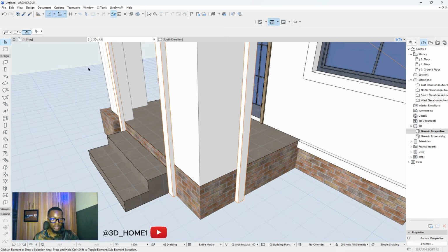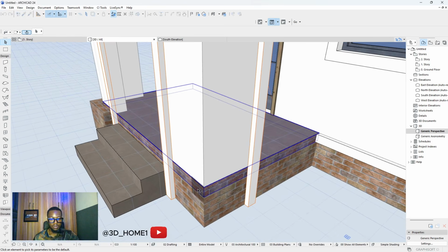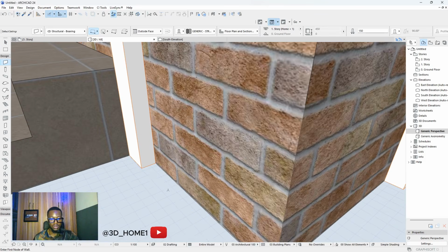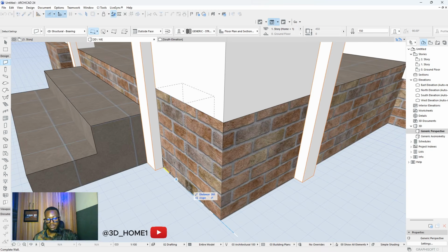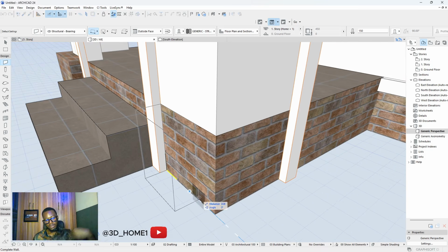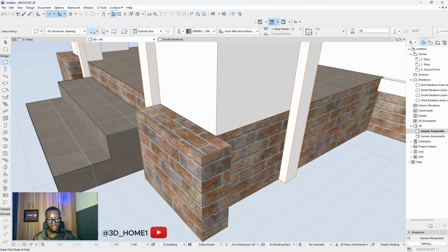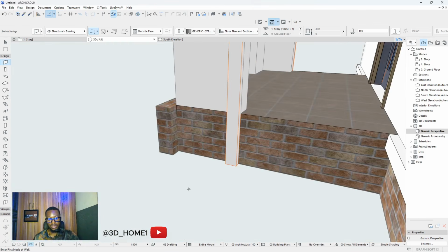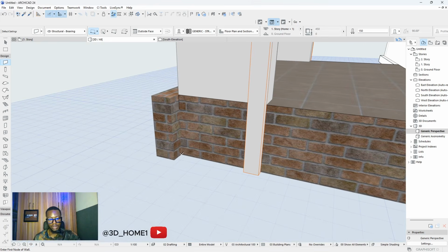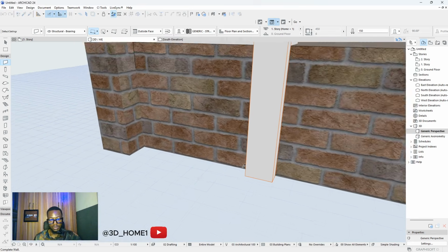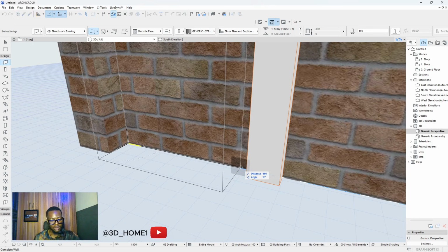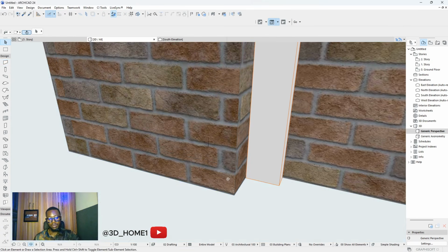We'll just click on, we pick up parameter, we'll select the wall, this down wall. So click from here. If the wall is inside, just press P to come outside. Okay, then click here, and then let's rotate, take it all the way from here, bring it up to this point. Now let's lock this by pressing shift, then we'll select this point. Yep.